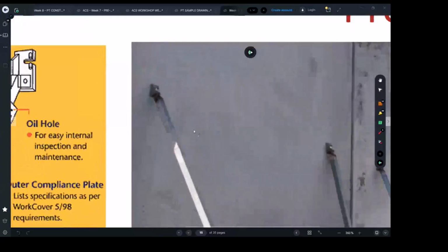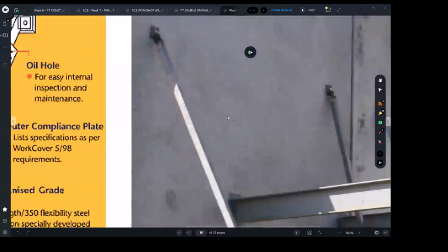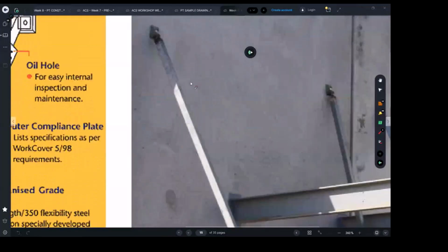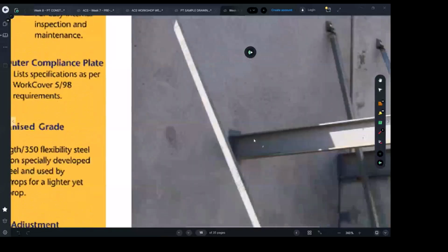But as discussed, those props will be taken away as soon as we build the roof and get those panels stabilized. And then those ferrules will be capped by a piece of plastic, which is provided by the supplier. They cannot leave it permanently open. They typically cover it with special covers provided by the suppliers.